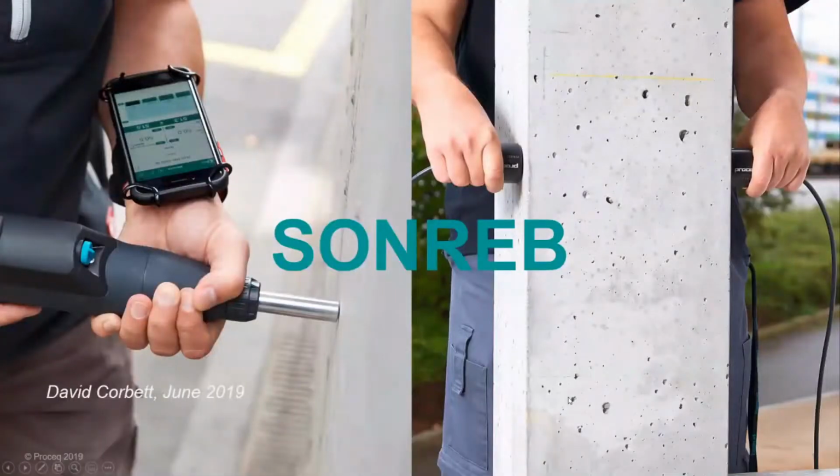Hi, David. Yes. Okay. So, SONREB, as Logesh mentioned, people use ultrasonic pulse velocity also for strength testing. In Europe, we have the EN 13791 standard for compressive strength testing on site. And it basically has exactly the same standard for two test methods. One's the rebound hammer, and the other is ultrasonic pulse velocity testing. That's ultrasonic pulse velocity testing alone.